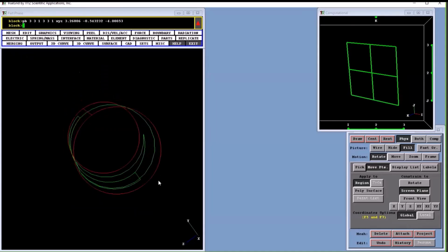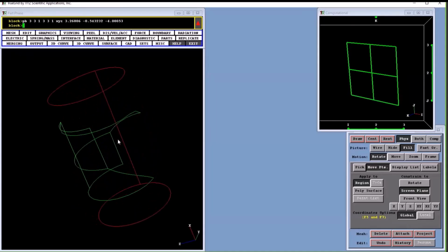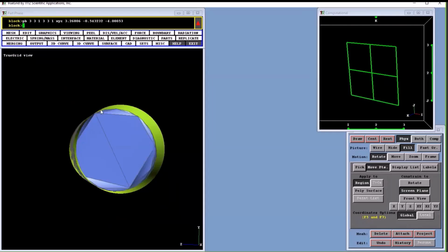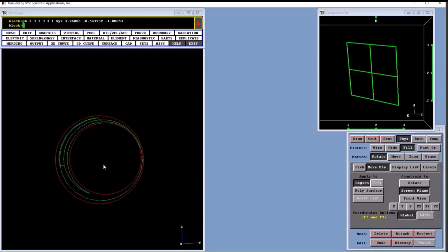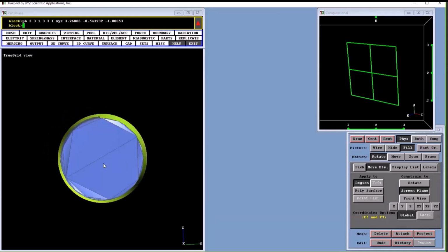Well, in this case, I took this particular vertex and wrapped it around more than 180 degrees, so that the edge that came to that vertex started out wrapping around this way, but at some point it was shorter to go this way. And that teaches us a lesson that when you project to a surface of curvature, never try to get too many degrees of curvature between two vertices of your mesh.